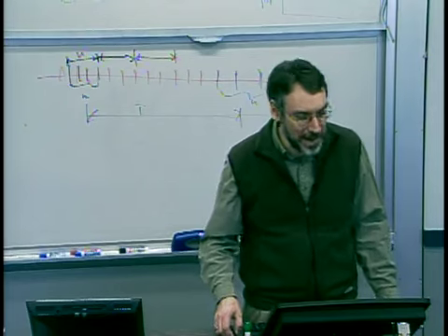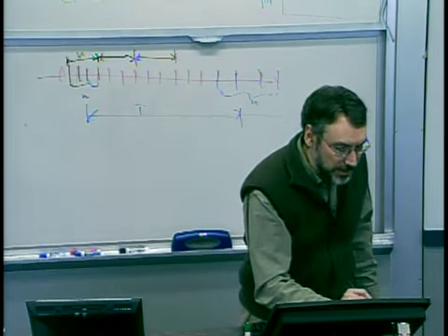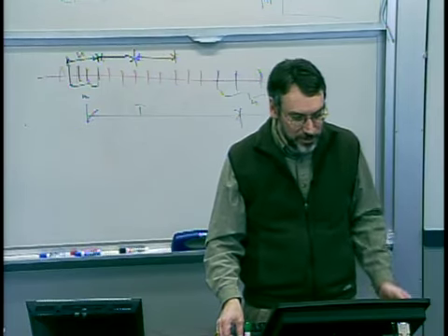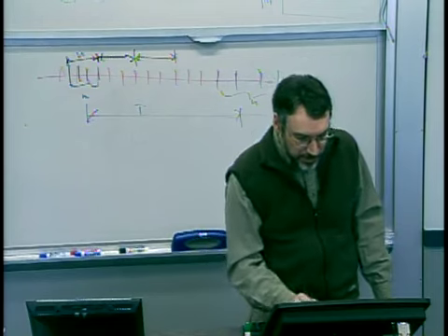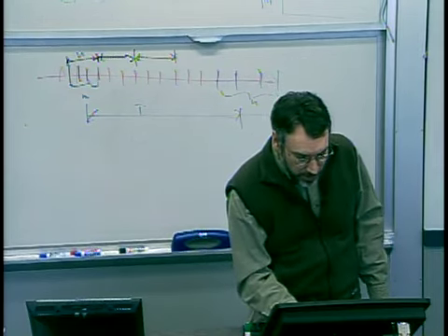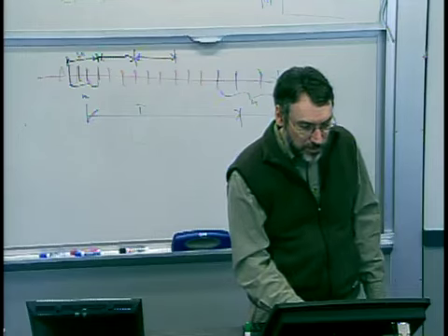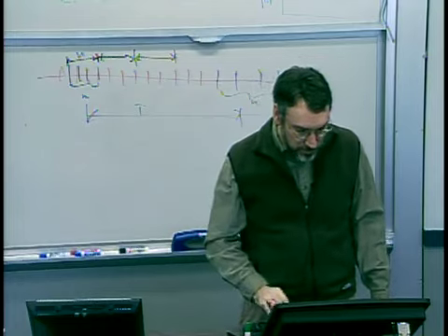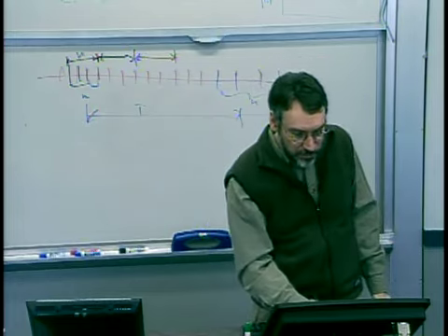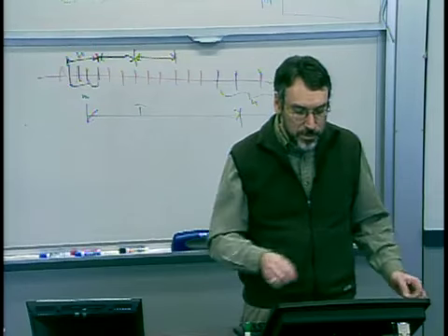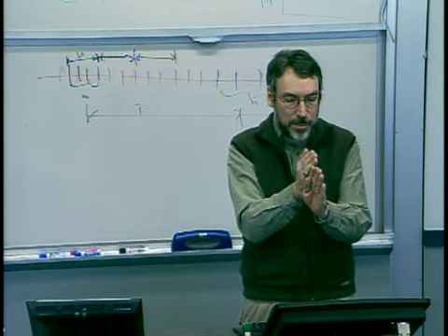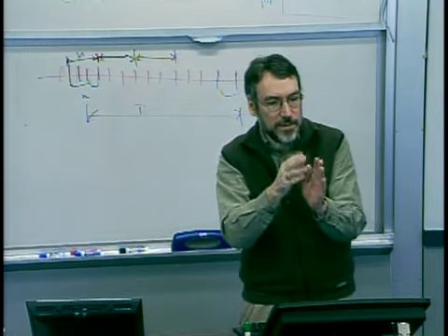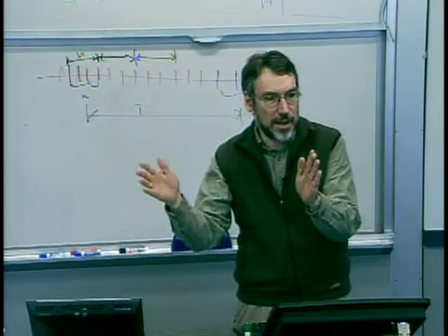There is an autocorrelation function, this RXX, as a function of the time separation or the number of sample points between them that has this definition here. If you think about it in terms of the time for an autocorrelated function that is, in fact, inherent in a linear first-order system, the autocorrelation function drops off fairly rapidly from zero time gap. So if I sample at this point in time and I go some time away, the similarity of those sample points decays away.